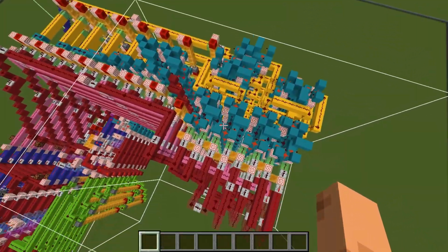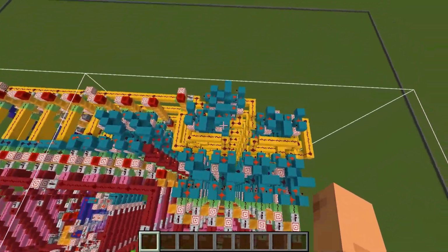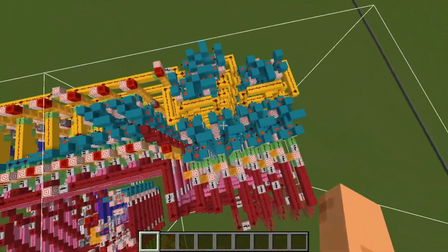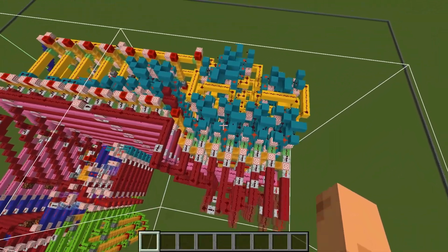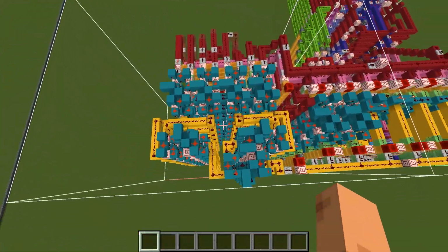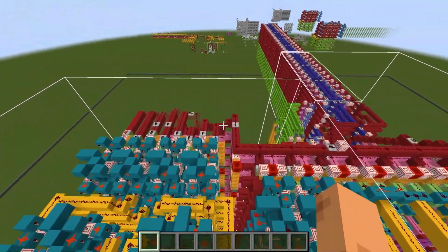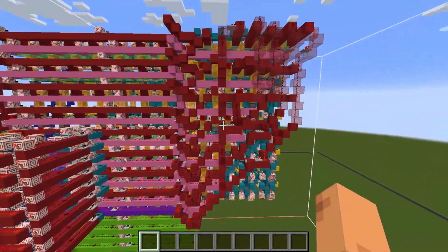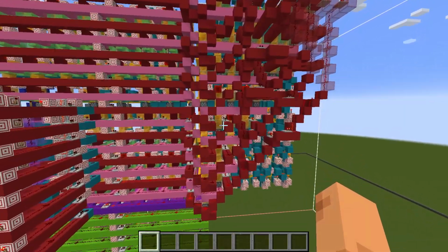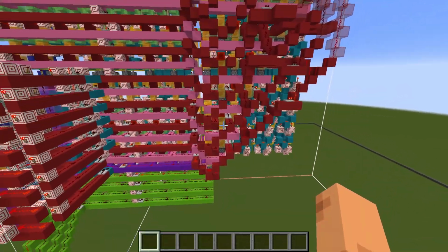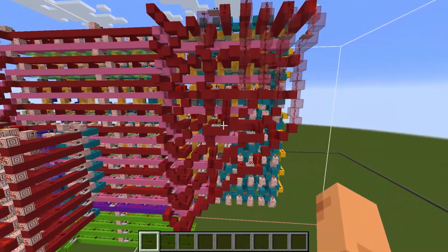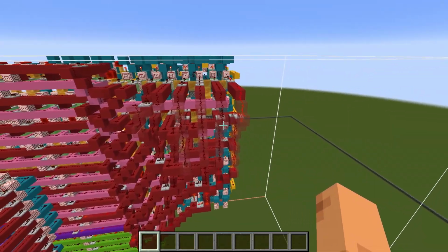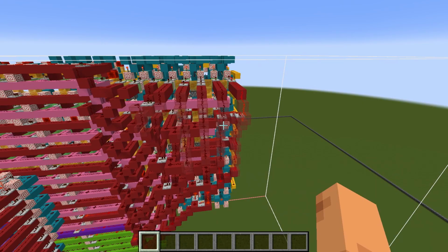But the main logic of a multiplier is not much different from what you'd learn in grade school for multiplication, where you just do a bunch of sums and some carries and combine them all together. You can get an idea of that from this mess of wires here. This is basically shifting various bits from one of the inputs, like shifting over the digits.